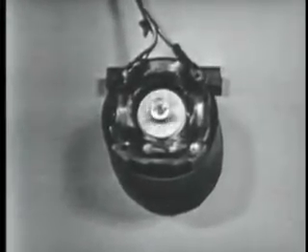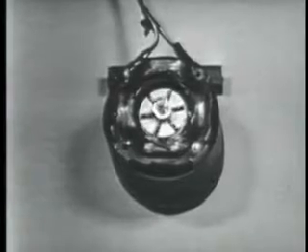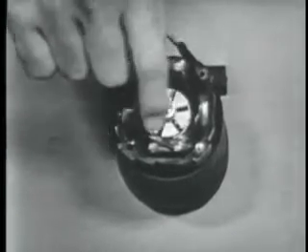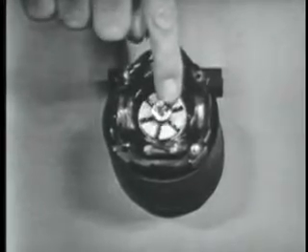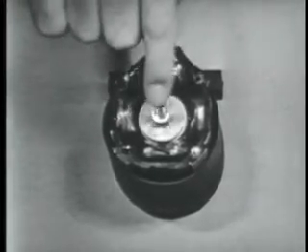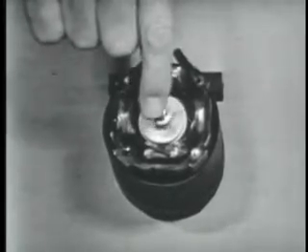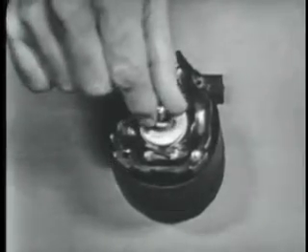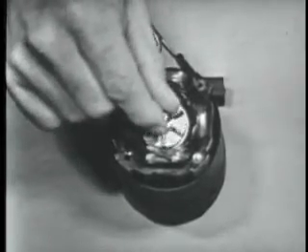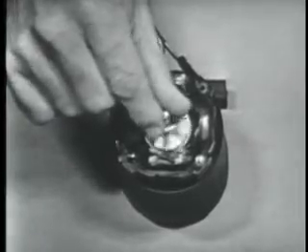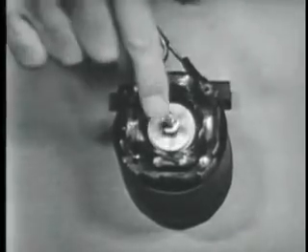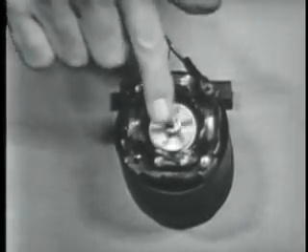Which brings us to item 5, which I believe you can have. Exactly. All right, the rotor of the induction motor does not rotate as fast as the magnetic field because of several forces that act on the rotor. One, the internal load, that is rotor weight, the little fan, the bearing friction, and so on, and the external load on the motor, such as the gears, pulleys, or the fan blade, or in this case, my finger. As I squeeze it a little bit, you can see that it turns slower. Right. Whatever work the motor will do. So the rotor's got to go slower than the rotating magnetic field in order to have relative motion so that it can become an electromagnet.